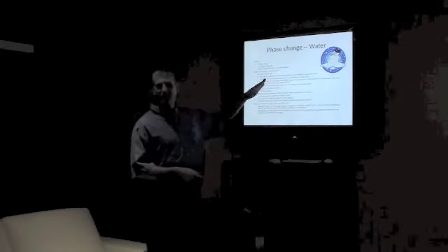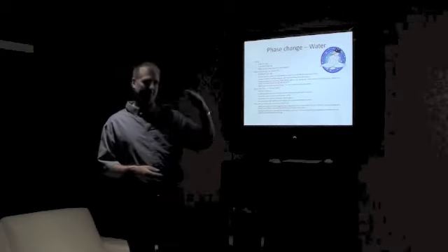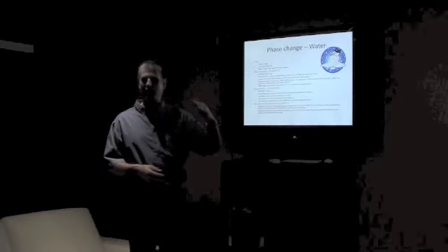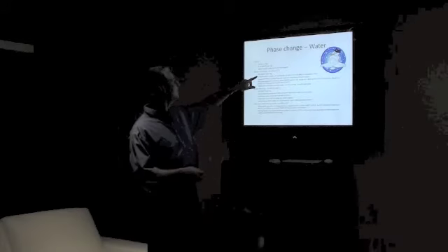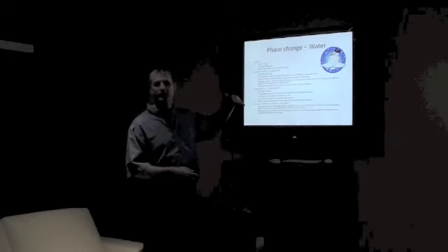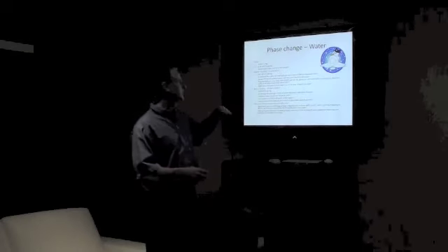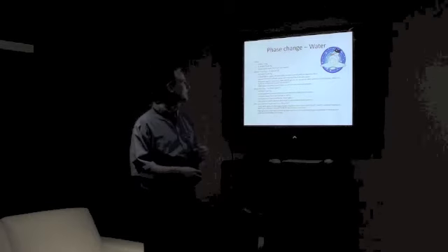Freezing water at about 0 degrees Celsius. In order to freeze water, if you take energy out of water, the temperature will drop until it gets to the freezing point. And then you can continue to take out energy. You can take 92 watt hours out of your kilogram of water, and it will freeze, but the temperature won't change. It will stay about 0. Then once it's frozen, it will continue dropping in temperature again.